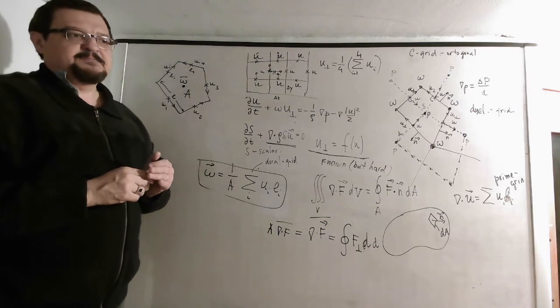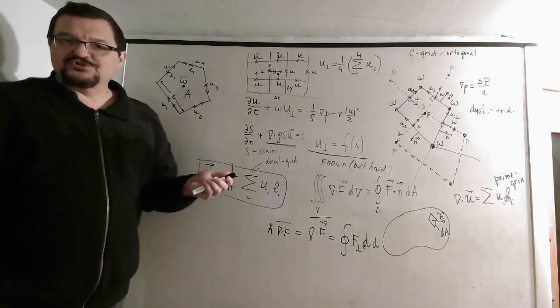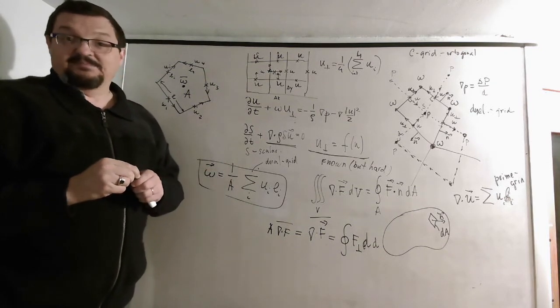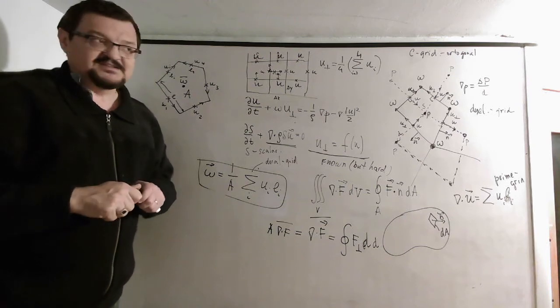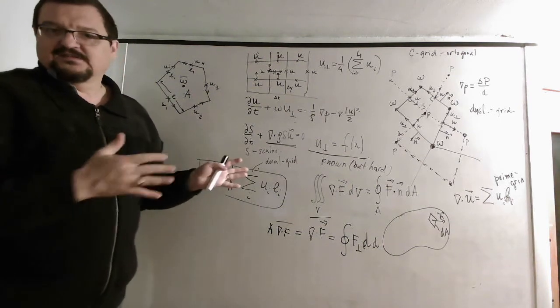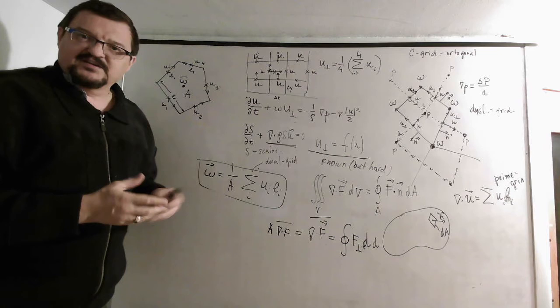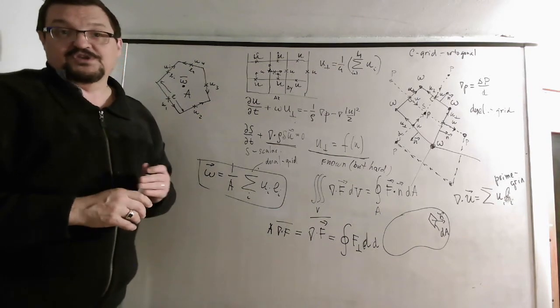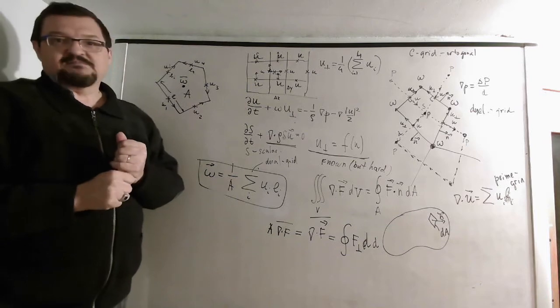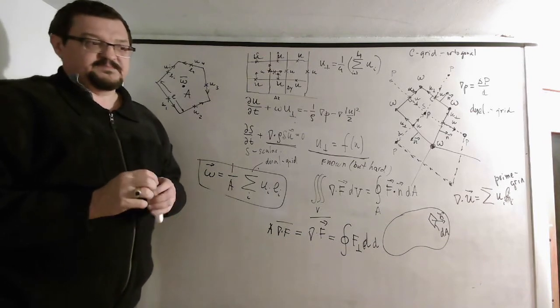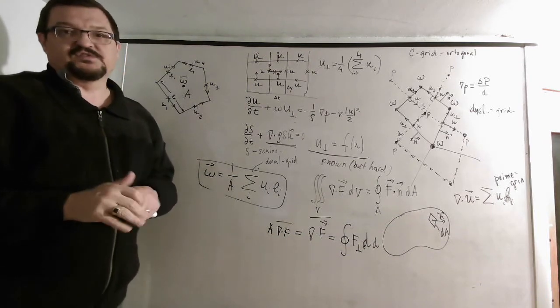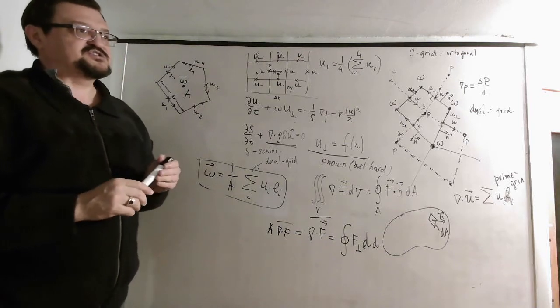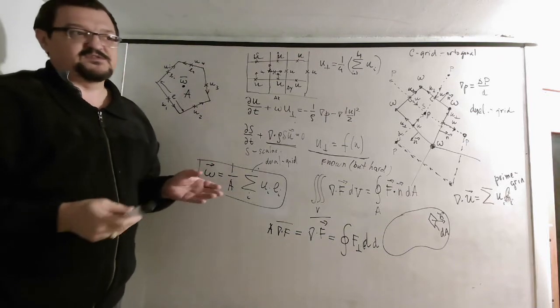It's some bogus solution that is completely numerically generated, that has no equivalent in the physical solution for that wave. So it's the so-called computational mode, and sometimes those modes can be very persistent and can distort your solution pretty substantially. So there are ways to fight those modes.